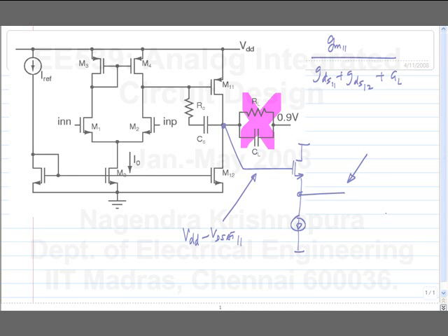And you can drive a capacitive load with a large gain, okay. But this may still be preferable. The two-stage op-amp gives you a higher swing, right? In that case, you get a higher swing as well as you get a high frequency second pole. Okay. So, what was your question? Whether you can drive?